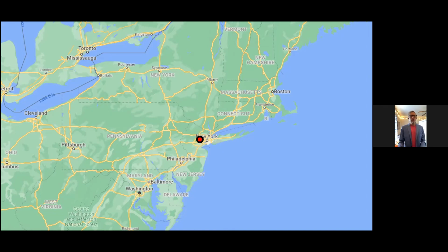So before, let's say PJM had a power plant in place as a contingency in case this transmission line trips offline. Let's say it was carrying a gigawatt. You've got a gigawatt of generation somewhere else that's on standby, ready to jump in when needed. So that's fine. This transmission line trips, that contingency gets put into place. Everything's fine. They weren't prepared for another 1.2 gigawatts, or what's probably closer to 2 gigawatts today, to trip offline. So that's like 2 more power plants that they would have to have spinning as a contingency.